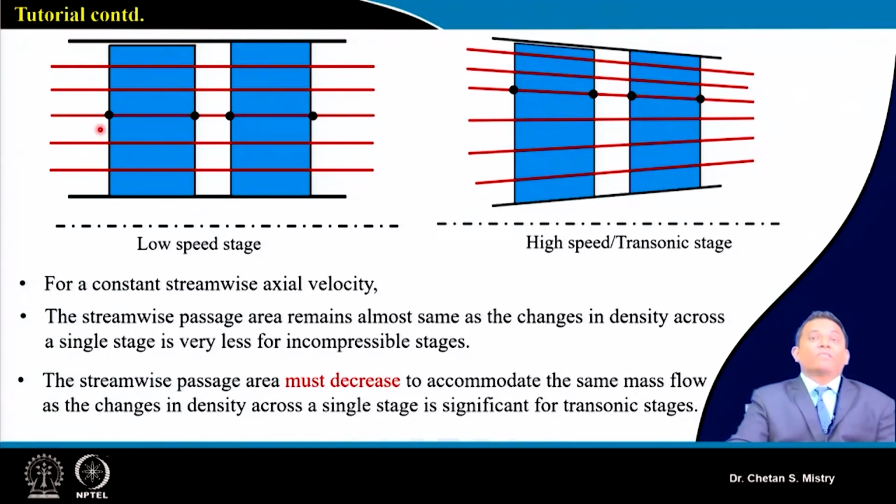Now this mid station, for the subsonic compressor we have discussed, is in all the designs done at 50% span. Then after that we will be dividing the whole span into an equal number of divisions. Maybe you can take 10 stations, 20 stations, maybe more than 20 also. No one will stop you. It's you as a designer who needs to decide. The more stations there are, the easier it will be to make those blades, and that will give you a smooth curvature for the blade.